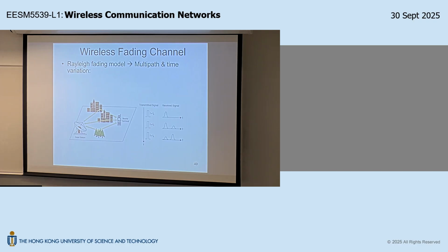Now, in the context of a cellular network, one performance metric is coverage. When you set up a base station, how far can this base station cover, right? So in a region where you have heavy path loss, let's say alpha equal to 4, as I said, if you double the distance separation, your receive power will already reduce by 16 times. So in a market with a high path loss exponent, the base station with the same power amplifier can only cover a much shorter range, right? So with respect to coverage, path loss, of course, is your enemy, right? It's something bad. Because of path loss, you need to use a higher power amplifier to overcome the loss, right? So that is something bad.